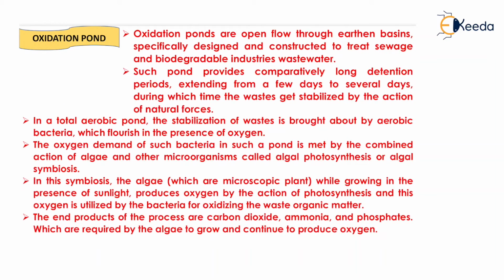Now we can move to the oxidation pond method. Oxidation ponds are open flow-through earthen basins specifically designed and constructed to treat sewage and biodegradable industrial wastewater. Now, what will happen in this oxidation pond?